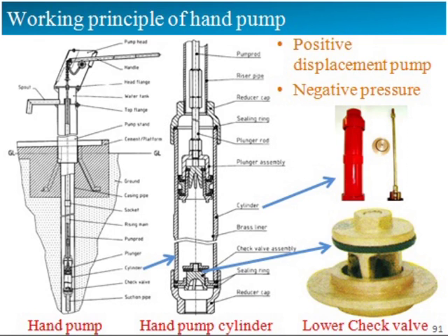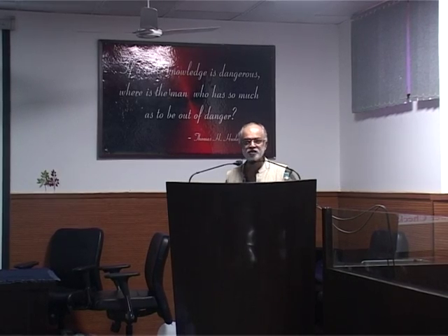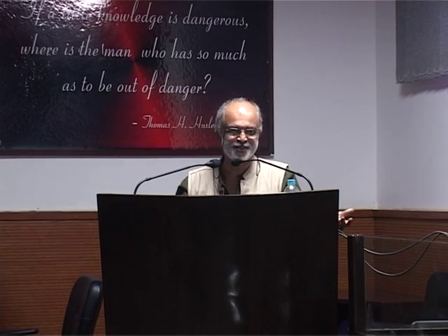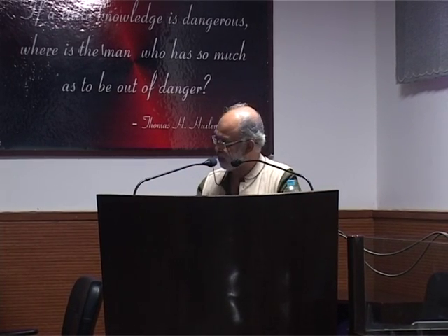So the liquid comes through here and comes out through this in the form of an annulus. So there are multiple liquid jets which are coming out. Now if I control the area available for this particular jet in such a way that the velocities are same as what velocities are obtained in the case of Bernoulli's equation, then I can create cavitating conditions in this particular region. And if I use these cavitating conditions, the water which is being pumped is going to be effectively sterilized, effectively devoid of microbes. Right? This is exactly what was done.